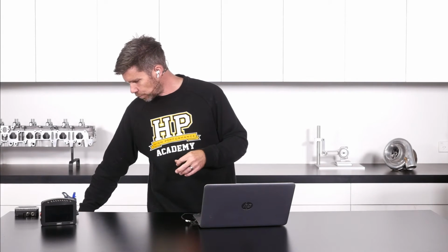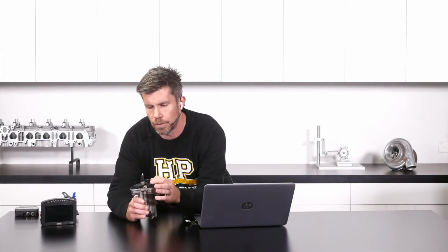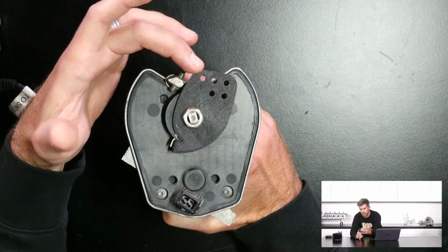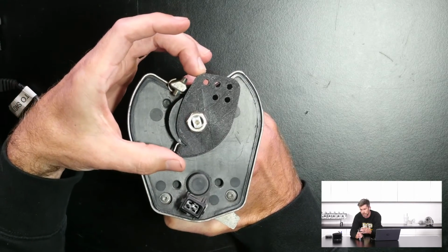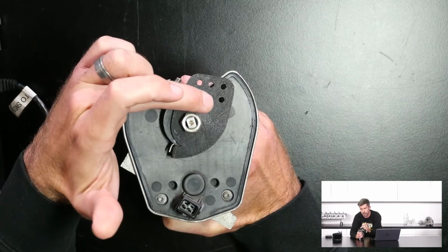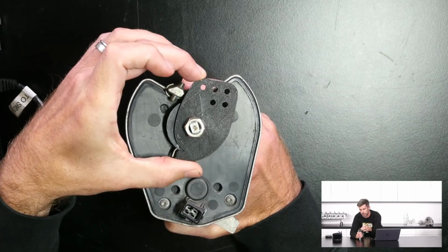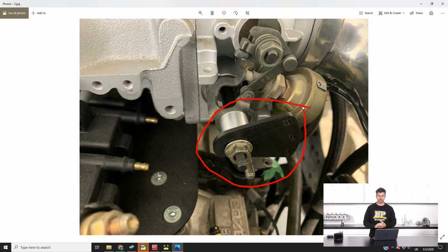So again, Brandon got out the 3D printer and Fusion 360. So if we jump to our overhead camera, he's removed the factory drive or bell crank off the drive-by-wire motor and designed this. Again, obviously the finished final product isn't going to be in plastic, but it's also got a range of different mounting locations which allow us to change the motion ratio and make sure everything's going to work. At the same time, the same sort of performance was done to the throttle body, and you can see we've got another bell crank that's been designed there.